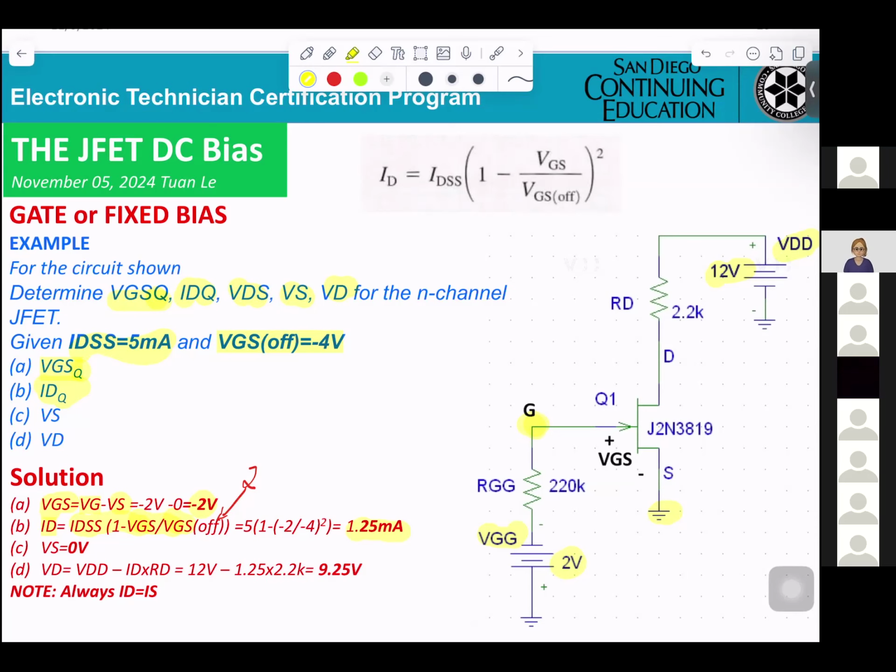Then now we go to get the VS. That's easy, right? VS means connected to the ground, 0. And the last one, VD. VD means the voltage here. Basically, it will equal VDD minus the voltage drop across RD. This is the formula.